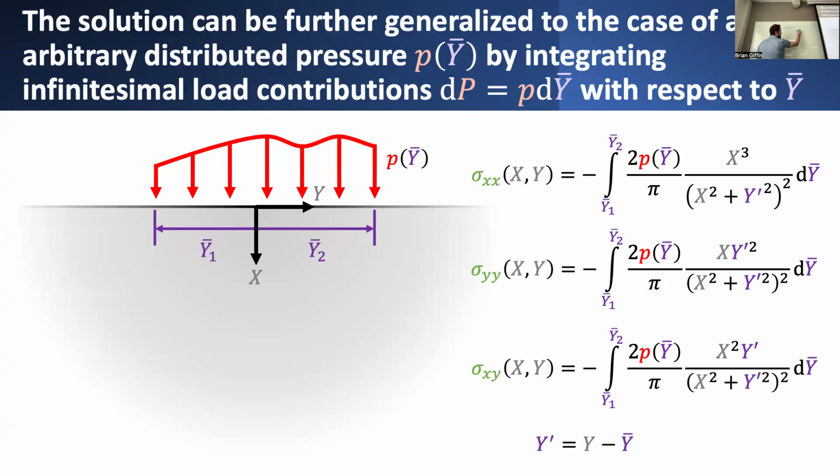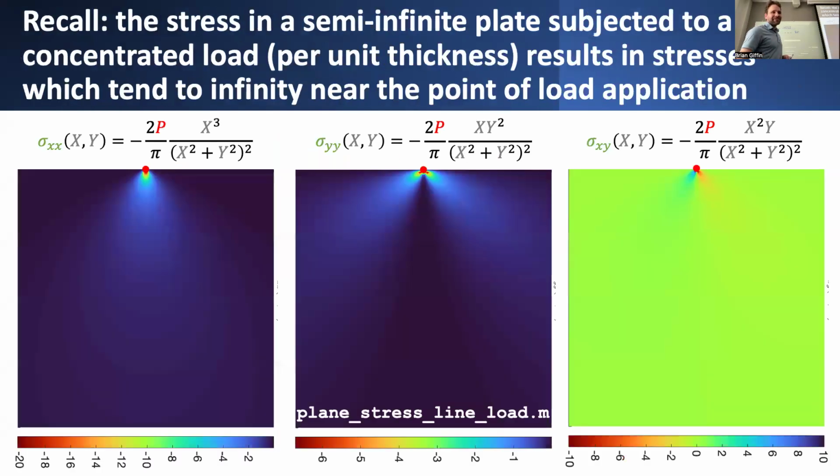Assuming that the soil itself has some self-weight, technically speaking, as you go further and further down, any soil above this particular line is going to include not just the contributions from the building load, but also all the self-weight of the soil that lies above that point. And in general, we have an idea of what this should look like.